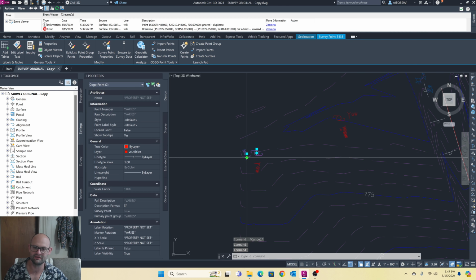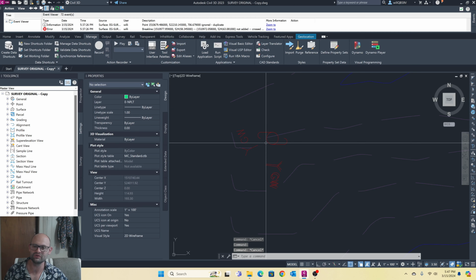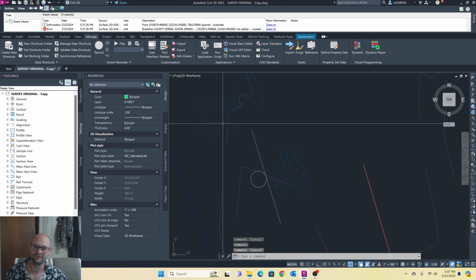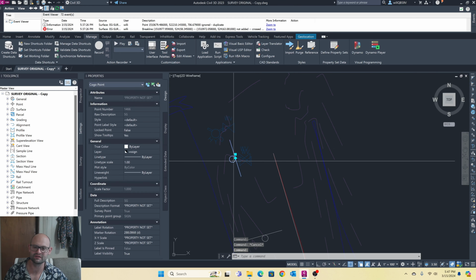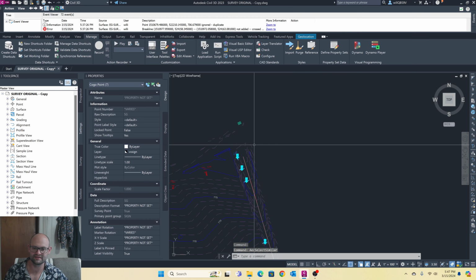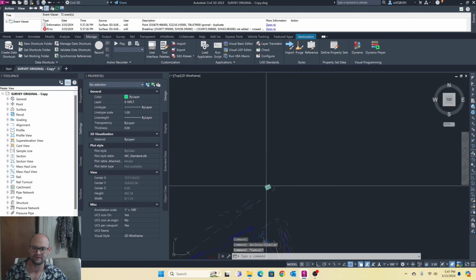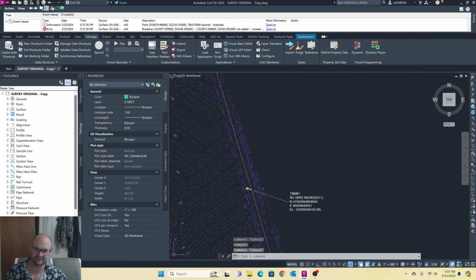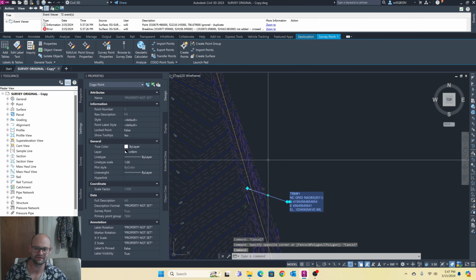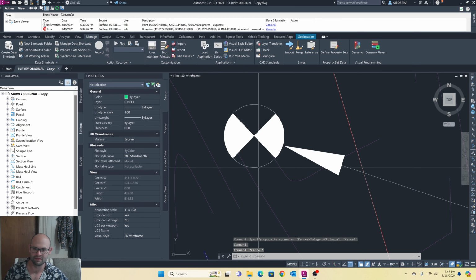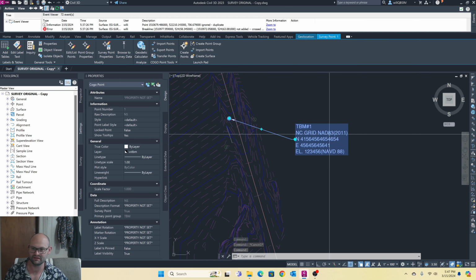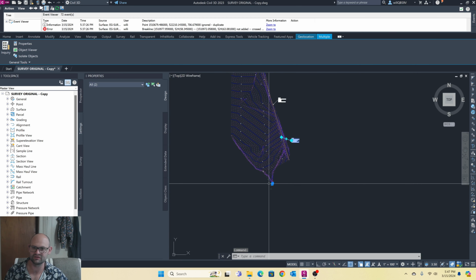So we got this guy wire symbol, this power pole symbol, valves, hydrant, it's like some signs, and that catch basin or drop inlet. Also got this Cogo point. We can go ahead and move it to miscellaneous along with that tie piece there.